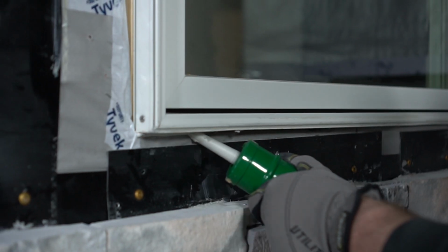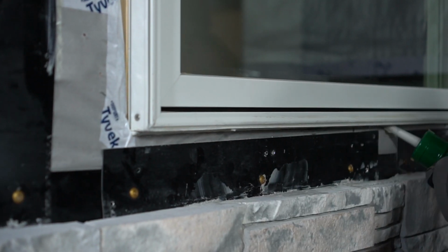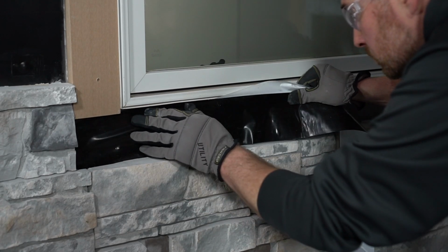Apply a bead of bedding sealant where the bottom of the opening meets the sheathing. Bed the top edge of integrated flashing into sealant and fasten panels or sills as per fastening instructions. Apply SAF over integrated flashing.